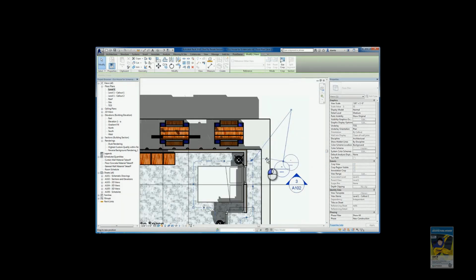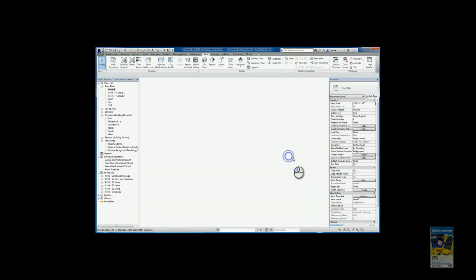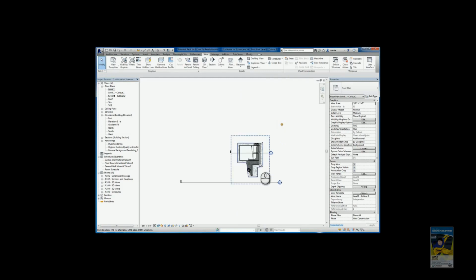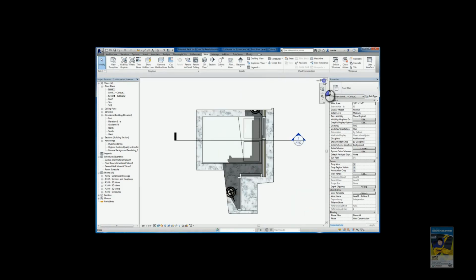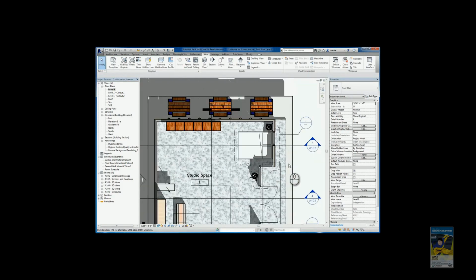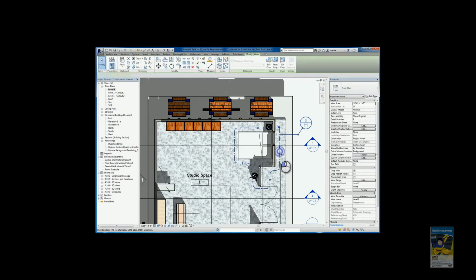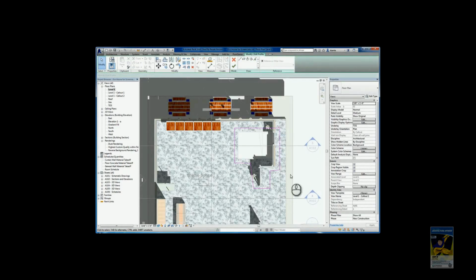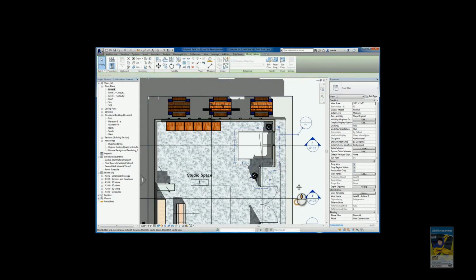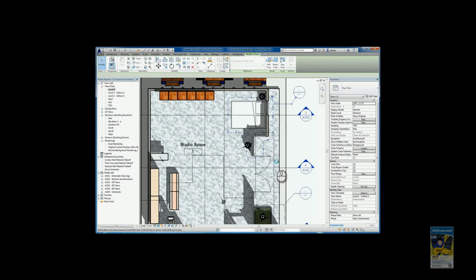And you can make the necessary adjustments that you need to make. If I double click it, it will take me to that callout, and it looks like so. When you're working with callouts, you can double click the symbology and it goes into sketch mode, and you can adjust the sketch work if you need to. That applies to non-rectangular and rectangular callout annotations.